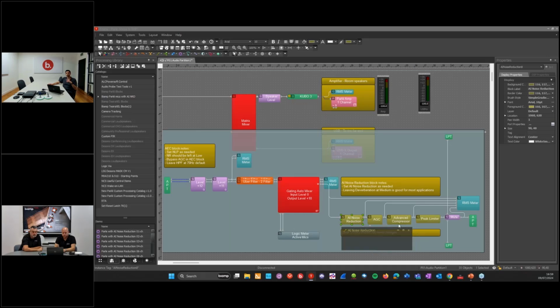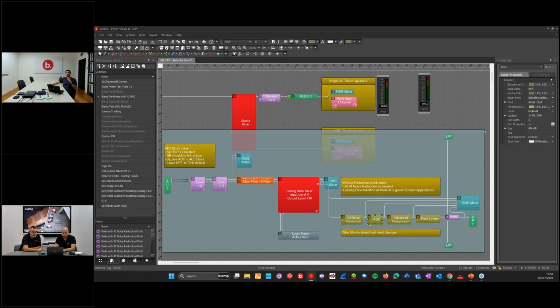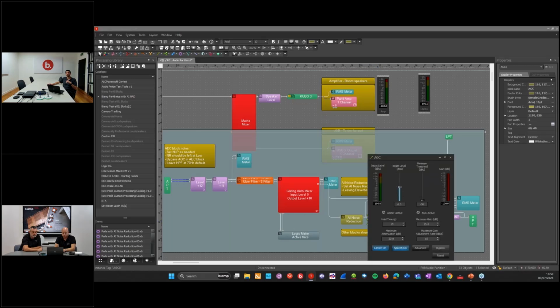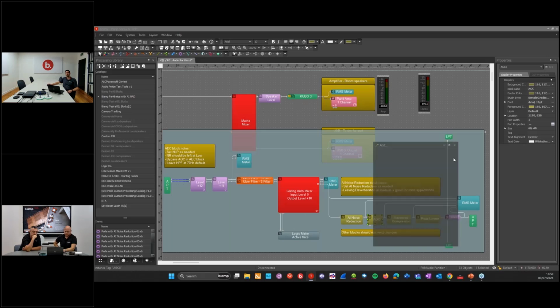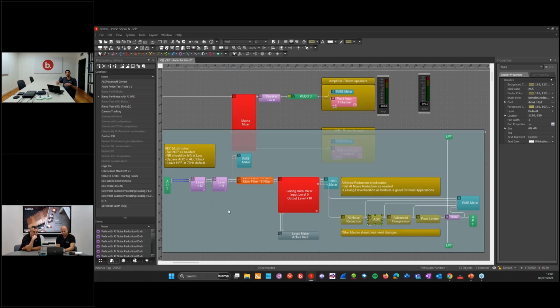And because we've done that, we noticed that the AI is so good at cleaning up, we can just use 1 automatic gain control after that. And this reacts very quickly, and it works spectacularly well. Because the signal coming into it is so clean, we can add and remove gain pretty much as we like without decreasing the signal to noise ratio in a way that actually hurts us. So what you end up with is a very clean, very clear signal that is extremely responsive to input signal fluctuations, and you get a very smooth, even output.